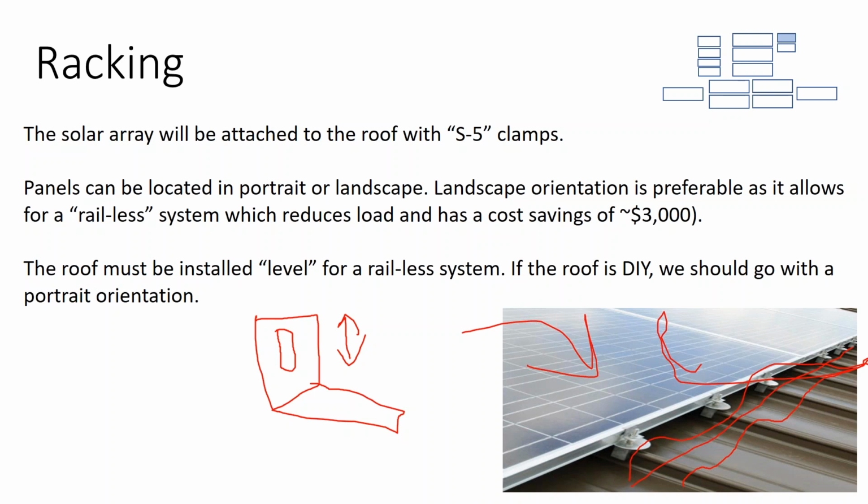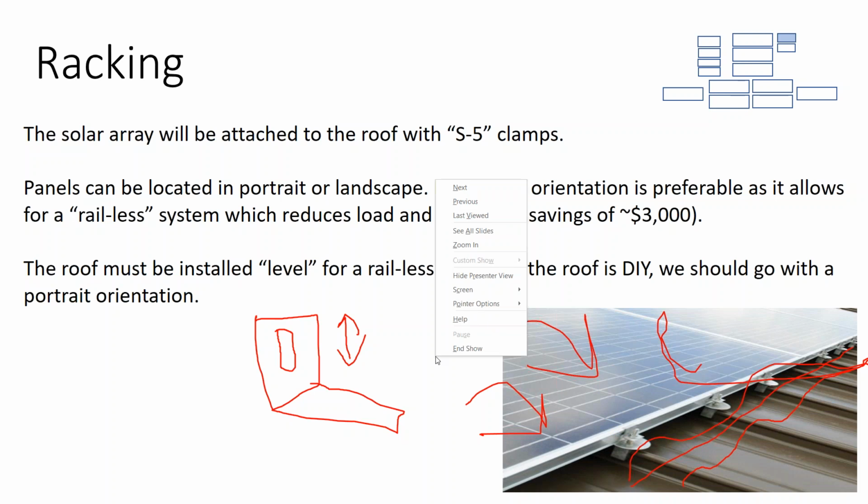If you're not squaring your racking system after you attach it to the rooftop, then when it comes time to bolt down the modules, the modules can start climbing up the rail, and visually it looks ugly. Particularly on residential racking systems, installers take a lot of pride in how their solar arrays look from the ground, and that's important. But when you get onto an older rooftop, and solar is often a retrofit on older rooftops, these railless systems cause those squaring and alignment issues to be even greater.